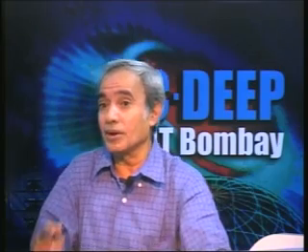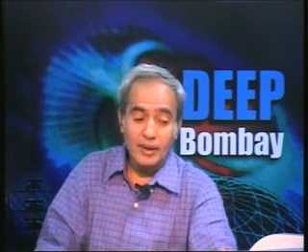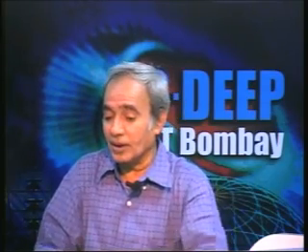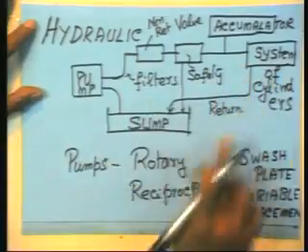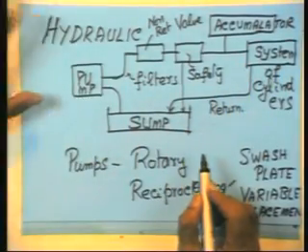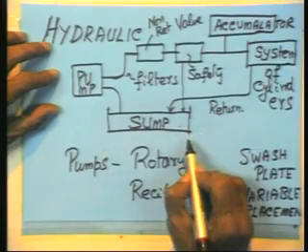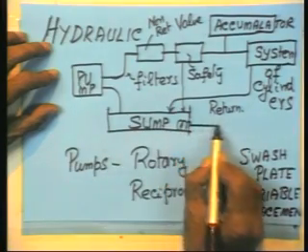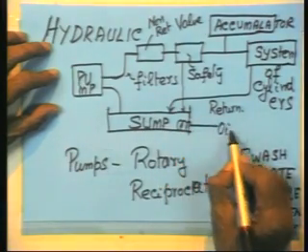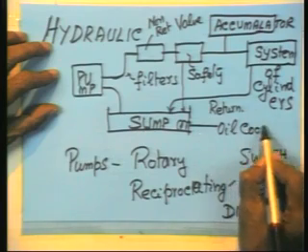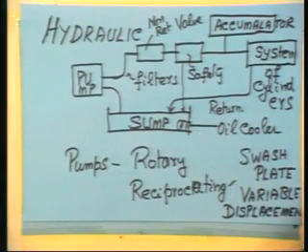In hydraulics also, you have to make sure there is no moisture to begin with in the oil. Because in the presence of moisture, oil starts deteriorating very fast. There is one more point here: as soon as oil is circulating, doing work, high pressure, low pressure, it tends to heat up. So there is always an oil cooler which is inserted into the sump.